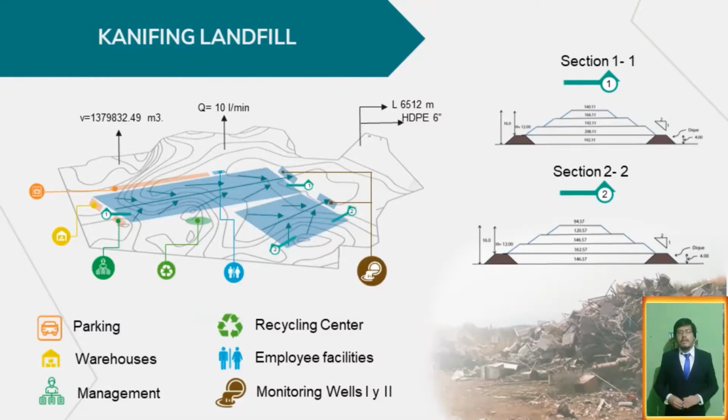Moreover, there should be 24 burners in stage 1 and 36 in stage 2. Also, there are 2 leachate ponds of 35 by 12 by 2 cubic meters in which leachate will be kept for 4 months. The volume of leachate is determined on the basis of the Swiss method based on the average annual precipitation in the area.